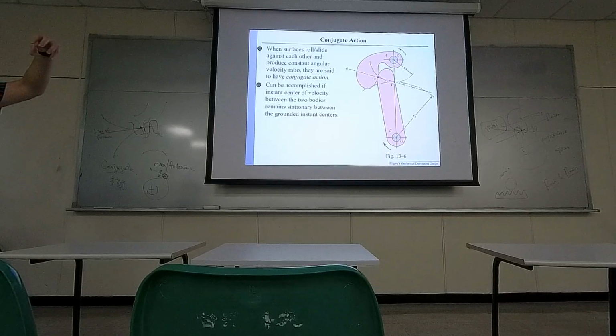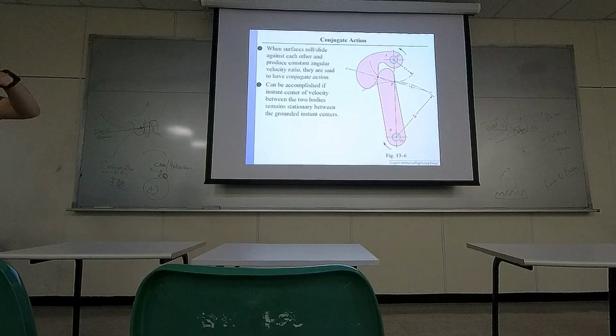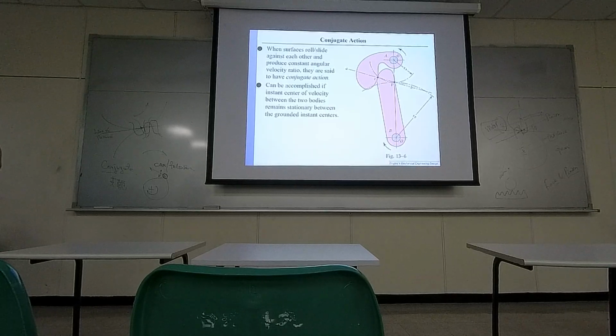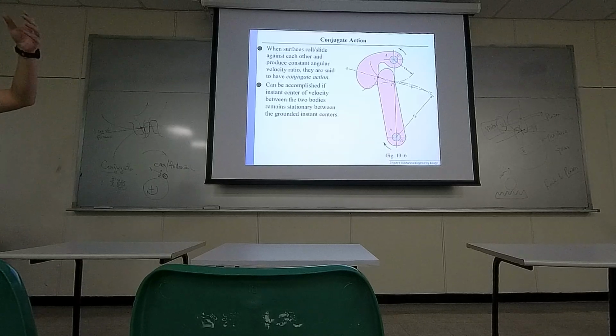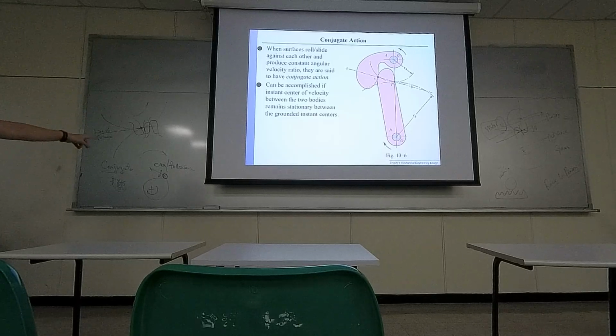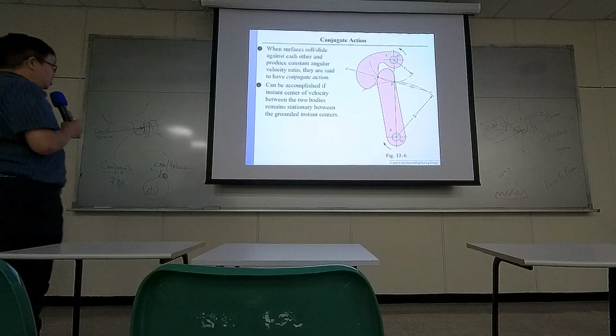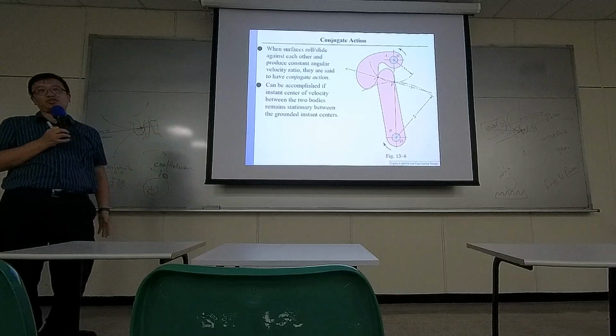So you always need a timely controlled valve opening a small hole for the gasoline coming into the engine, close it for explosion, and then open another valve, release the waste. So the valves are moving up and down in certain time sequence. Usually those valves are controlled by cam and follower. And the cam and follower is following conjugate actions. Okay?